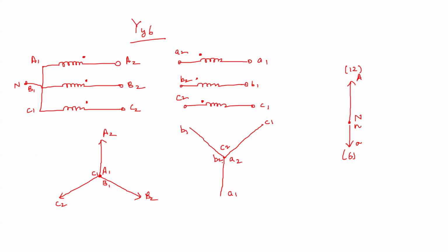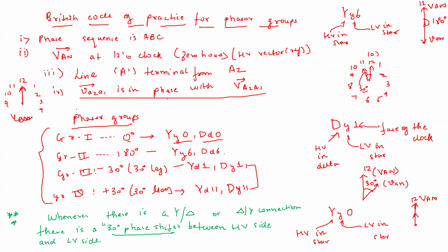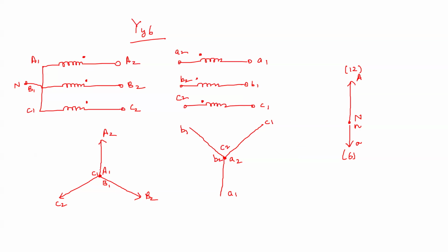So you see, when I followed that, automatically the vector diagram is telling you to short C2, A2, B2, so that this becomes a three phase diagram. It automatically happened. That is why these rules are important. You should take this diagram basically: if A2 is up, A1 is down, so you have to draw it that way. Similarly, when you are drawing, B2 is on the downward side and B1 is a little bit upwards.